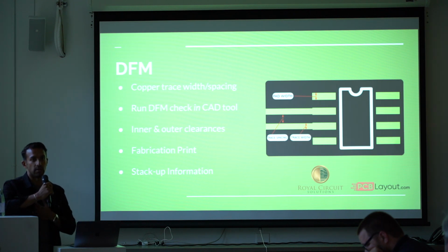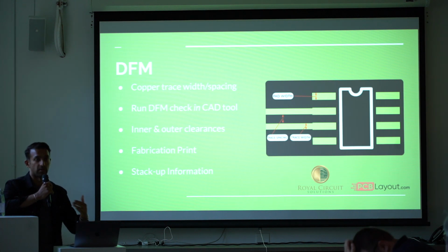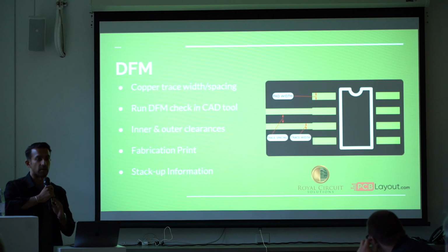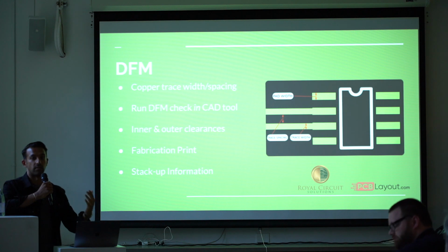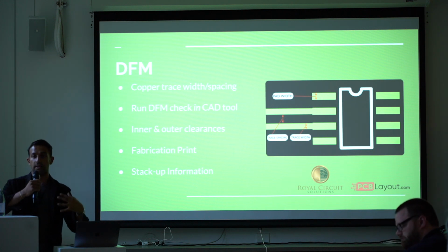This is something that we do. Other fabs do it, but we do it free of charge at the quote stage. Anything regarding the stack up. So if you need help with your stack up or getting to a particular impedance, every shop uses a somewhat different process for their etching and their plating, and all those numbers aren't known and calculated internally.